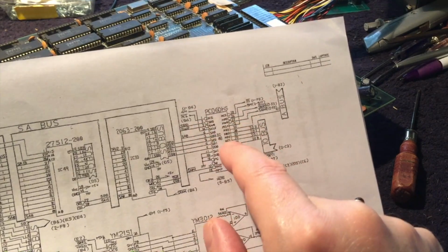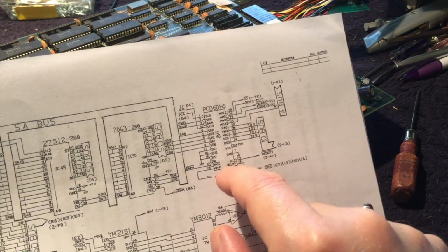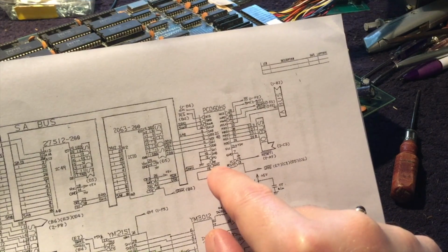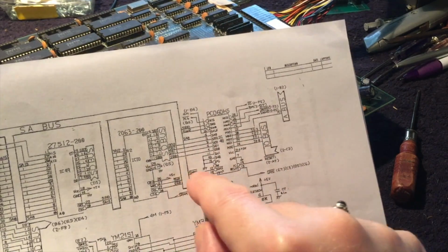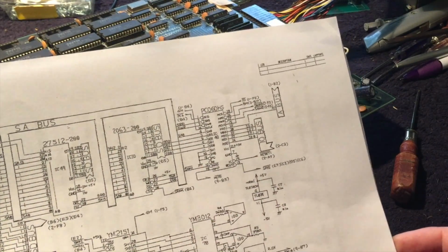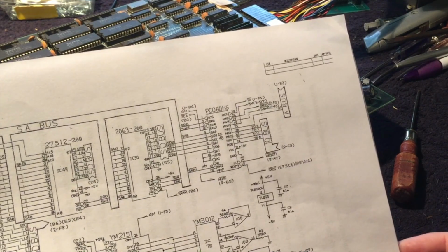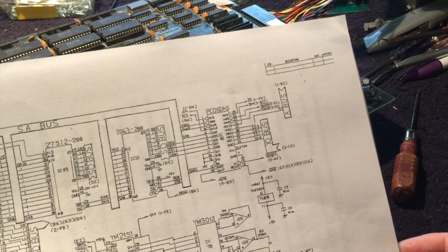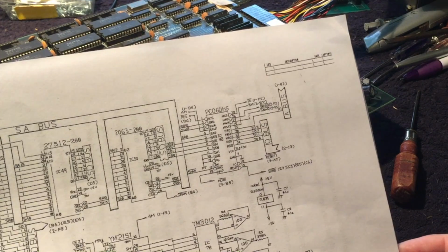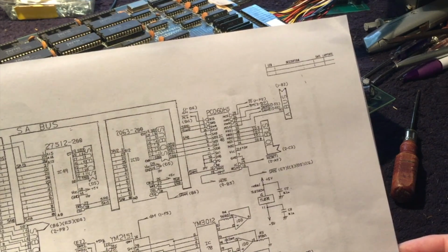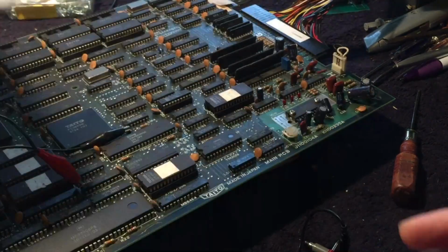And there's read and write lines, and there's the 4 data bits and an NMI, non-maskable interrupt, which I'm assuming means that when there's data being sent from the main CPU, it's going to trigger that NMI, which forces the CPU to listen to it. So let's see if that NMI signal is actually being toggled. When it's sending a command to play a sound or to turn on or off the music, the NMI line should toggle. So that's pin 12 on the custom.